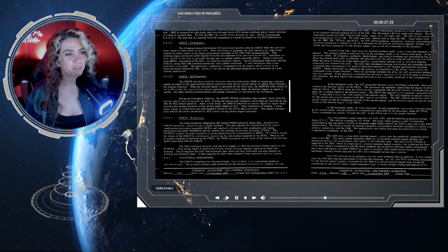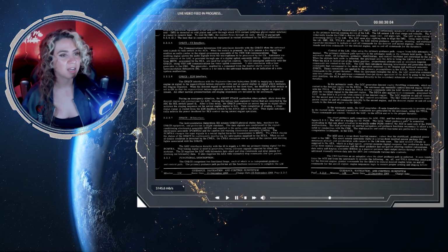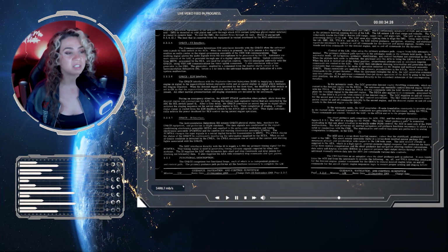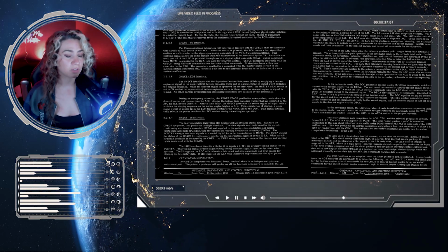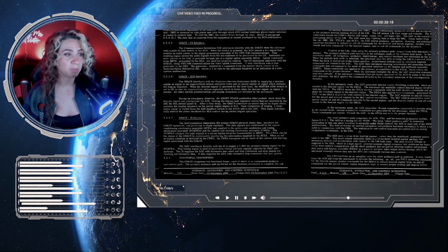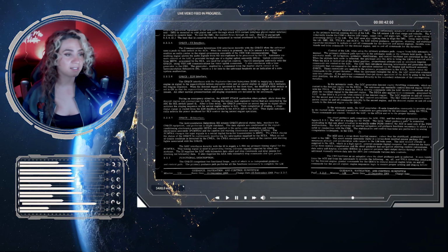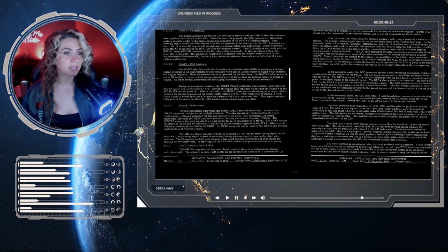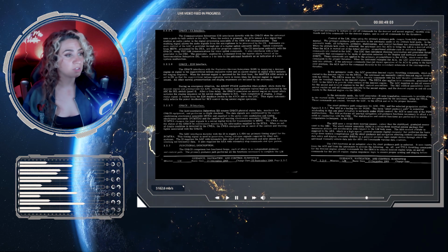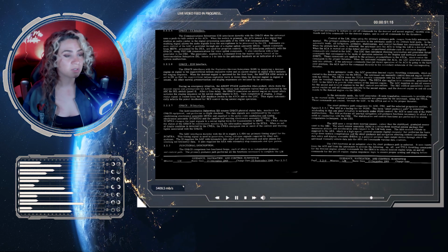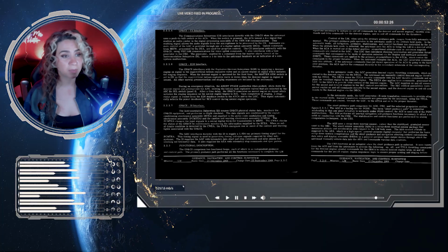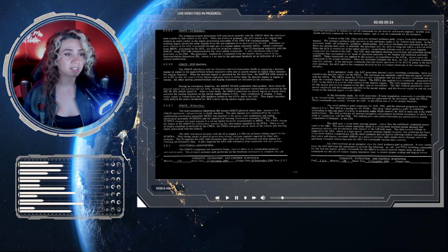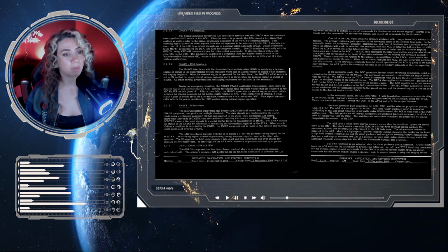The AGS performs all inertial navigation and guidance functions necessary to effect a safe orbit or rendezvous with the CSM. The stabilization and control functions are performed by analog computation techniques in the CES. The AGS uses a strap-down inertial sensor rather than a stabilized gimbaled sensor used in the IMU. The abort sensor assembly, the ASA, is a strap-down inertial sensor package that measures attitude and acceleration with respect to the LM body axis.